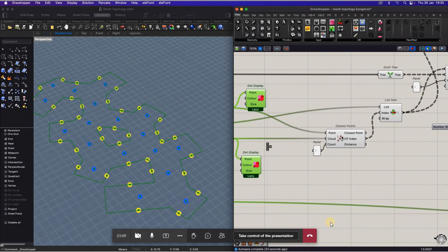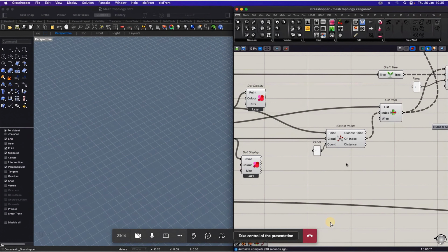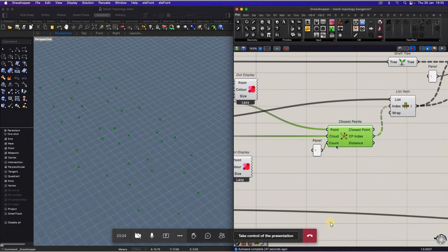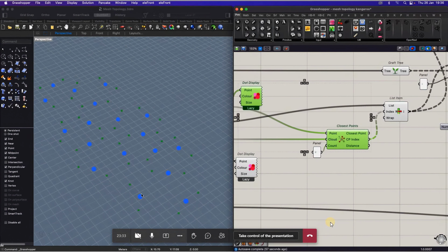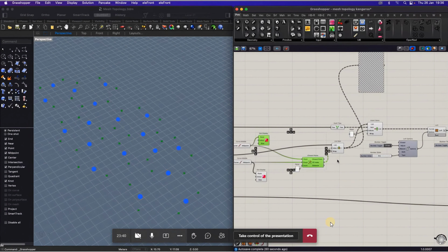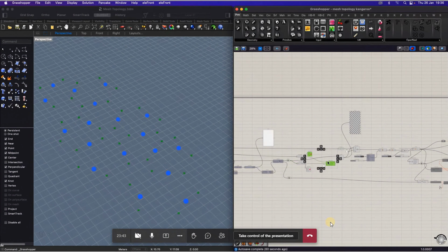And then a really cool component, which I didn't know about before. I knew about closest points, where you take a whole cloud of points and see how far they are from one point. But this closest points component can give you 2, or any number of points that are closest to center points. So which one is the center point? The blue was. This component will tell me the 2 nearest points to each one of those blue dots, which is once again so simple but so powerful. So immediately we can select those actual curves.